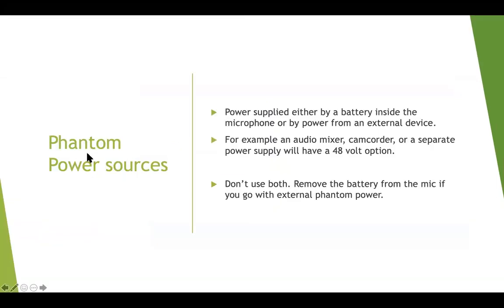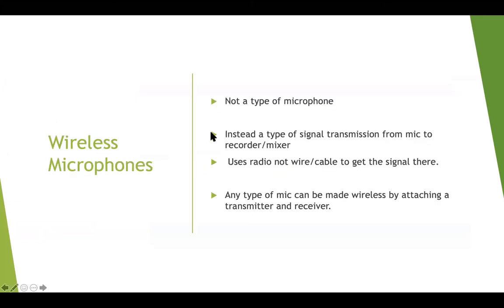When you use phantom power externally, don't leave the battery in the microphone. Some companies like Sennheiser and Neumann will have what's called a dummy, which is just a metal piece that replaces the battery. You put that inside the microphone instead of the battery. Some will operate without the battery in it. You'll find out in a matter of moments if there's no sound, it needs a dummy replacement. But never leave the battery in if you're running external phantom power, right?